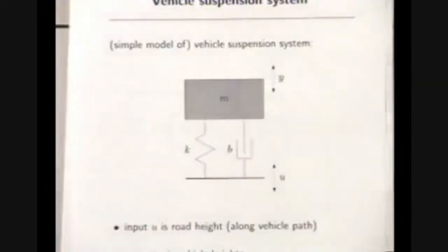Now in a mechanical system, that's probably a bad thing. In a suspension system, that's for sure a bad thing. In an electronic circuit where you're trying to amplify a sinusoidal signal, that's a very good thing. And that's actually why there they refer to the quality factor. The less damped something is, the better it is. So if you do RF or wireless stuff, your measure of merit is how resonant you can make something.